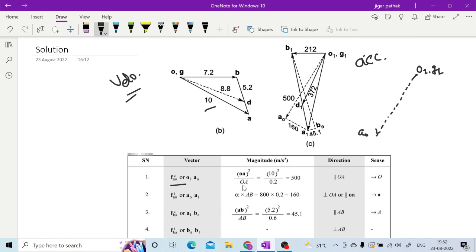So for that, as I have told you, first you are going to calculate this centripetal component, that is the linear velocity square divided by that link length, right? And then tangential will be calculated from the angular acceleration given. So angular acceleration is given for this crank, and it is perpendicular to this centripetal acceleration. So O1 to E1 will be calculated then, so you can have this particular vector O1 E1, which is nothing but the acceleration of E with respect to O, right?